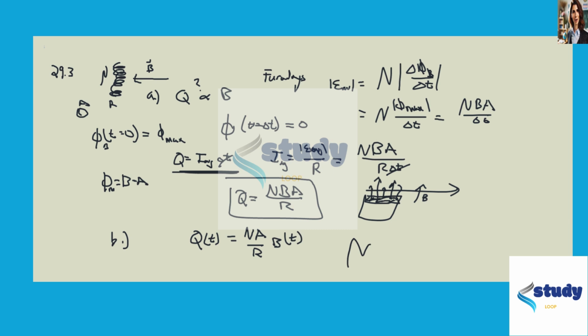So if you know a particular pattern of a B field as a function of time, the search coil is going to let you read out the charge as a function of time. You can just scale it by these coil parameters, and you can read exactly this information encoded in the magnetic fields of the card. So that's how these magnetic strip card readers work.